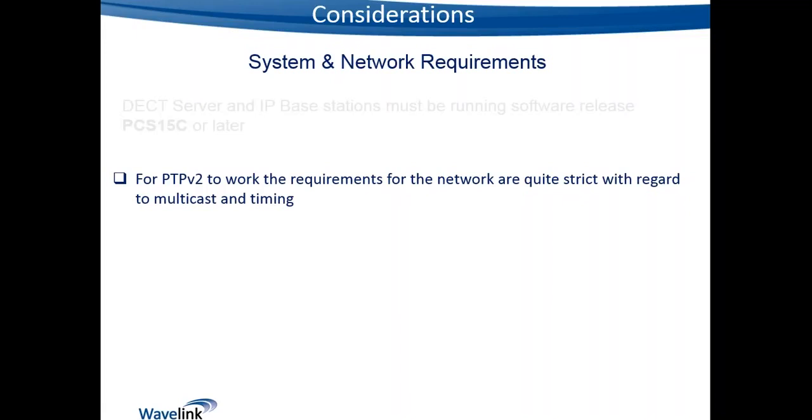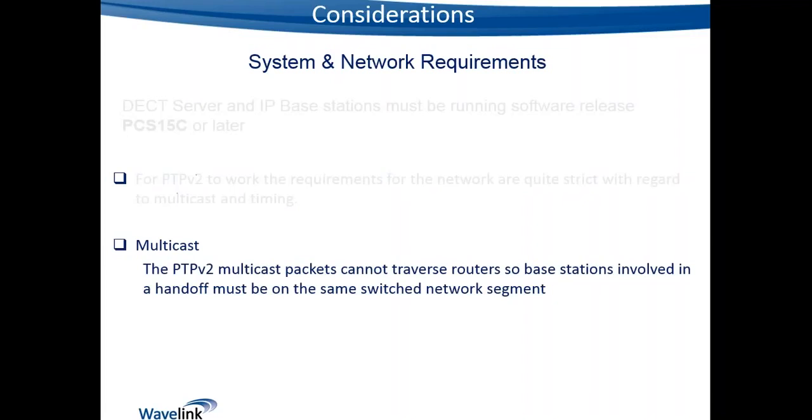We'd always recommend using enterprise switches so you can make sure those switches can manage the traffic in such a way that it's not going to introduce a lot of delay or jitter, which could impact the operation of LAN synchronization and the Precision Time Protocol, which uses a multicast methodology.